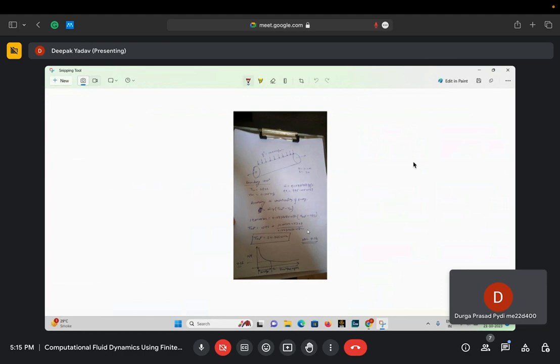So you were able to calculate the temperature distribution inside the pipe, right? Yes, the temperature at outlet, and on the wall. Were you able to get the temperature distribution on the wall? In heat and mass transfer, the given value of Nusselt number is 4.36, a constant. What I'm trying to ask is, basically you need the Nusselt number. So to get the Nusselt number, how do you approach it?